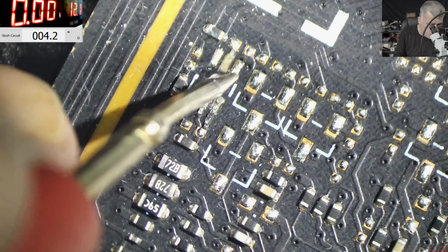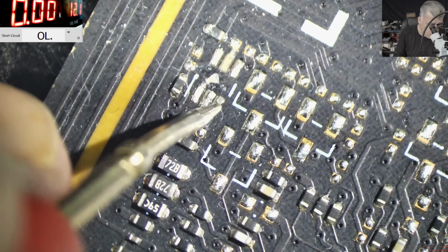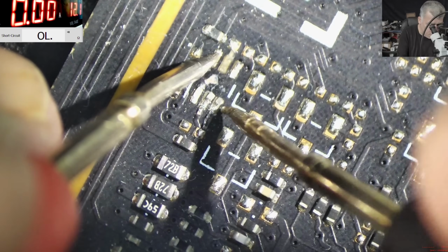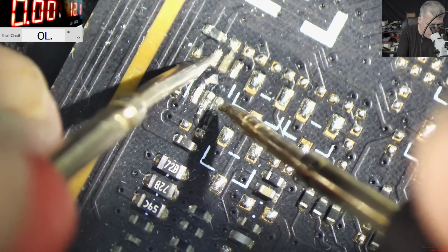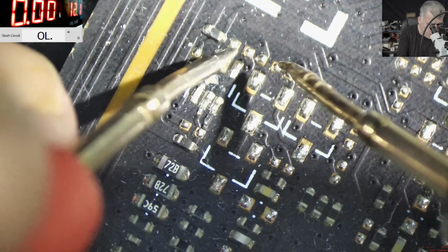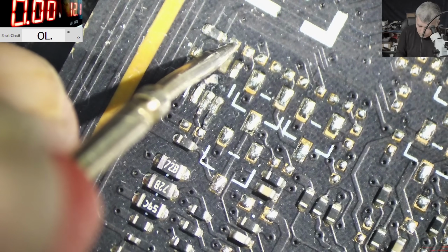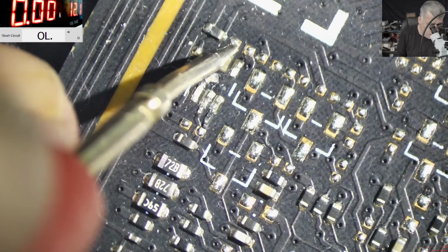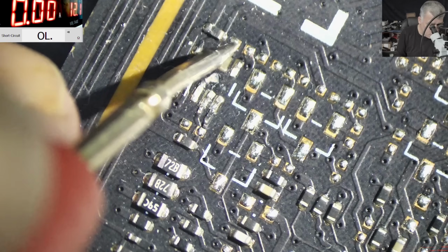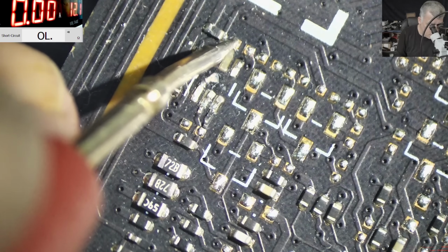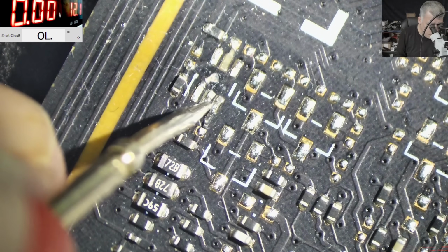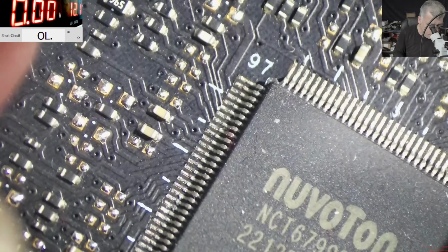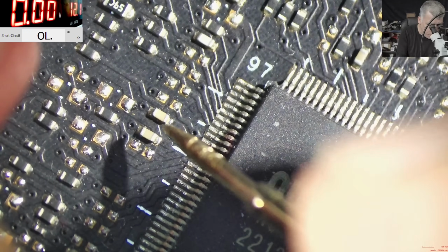Then you have this and this, which is ground. And here you have another 3.3, which probably is not together. No, it's not together. It's something else. And here you have 10 ohms. So what these 10 ohms mean can be a load, but we don't know that yet. So this 3.3, let's see where it's going. This 3.3 is from the main power rail.